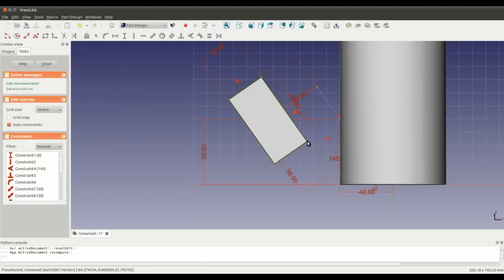Now I need to put a circle so that it pads into a cylinder which goes in this direction through the center of this first cylinder, with this point well defined, and by that I mean the angle here we've defined and the height we've defined, and it's coincident with the outside of the first cylinder.